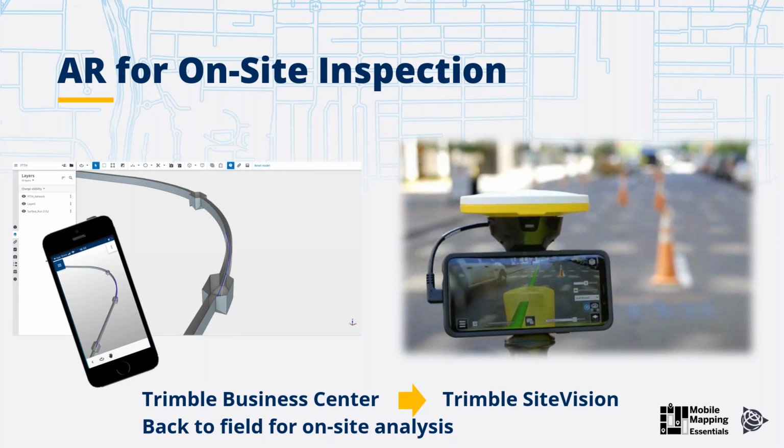And then once you have defined the geometry, you can decide the elements you want to include in your utility network, for example, manholes, the type of manholes, at which height with respect to the surface you are installing them, what the template of the trench you would like to build should be, where the utility line will sit, and what the clearances between the pipe and the sides of your trench should be.